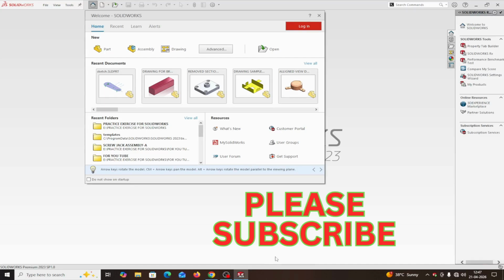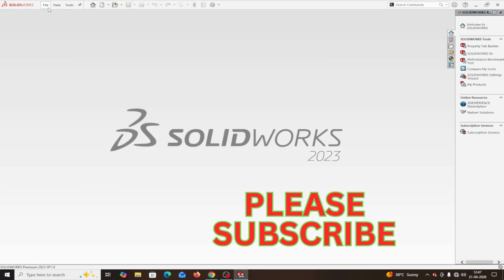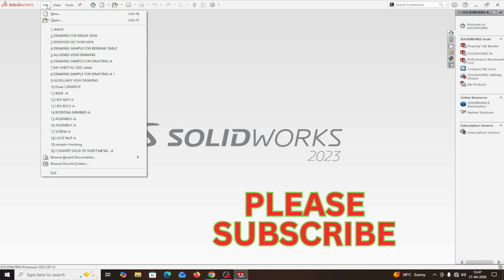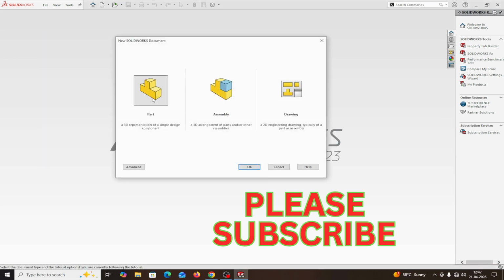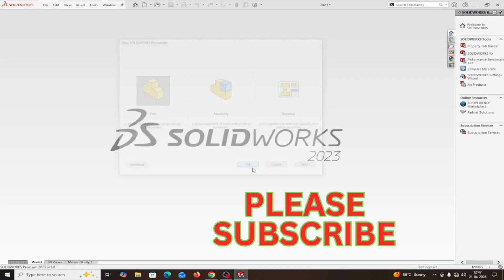Hello everyone. When you open SolidWorks, you will find this window. This is the welcome screen. If you want, you can go in from Part, okay, environment. But I don't want to go from here. Go to File, then New. This window comes up, select Part, and okay.